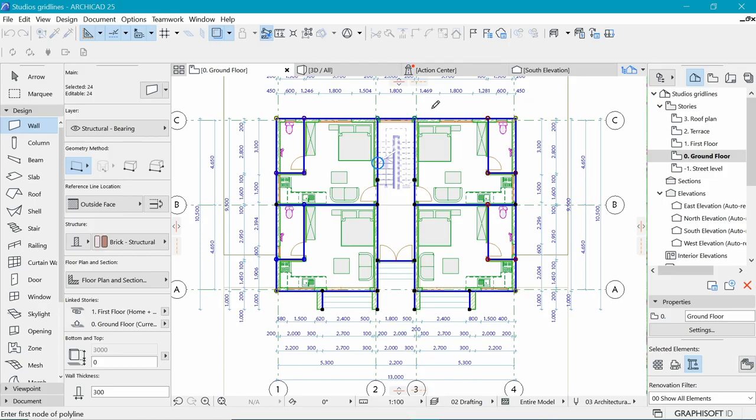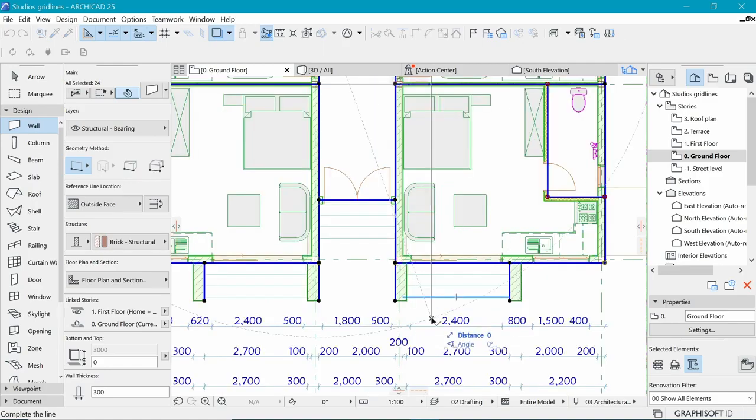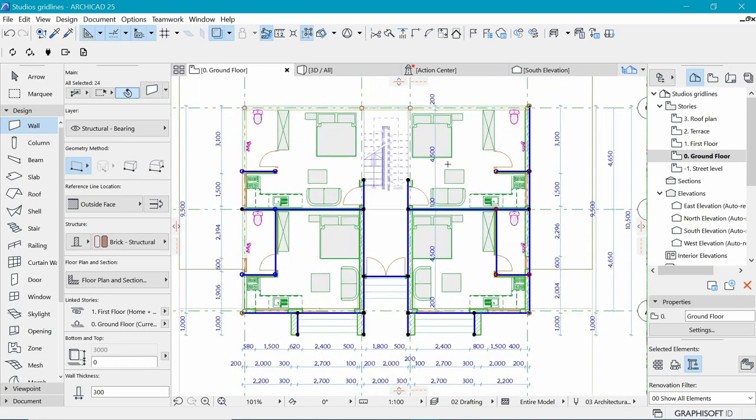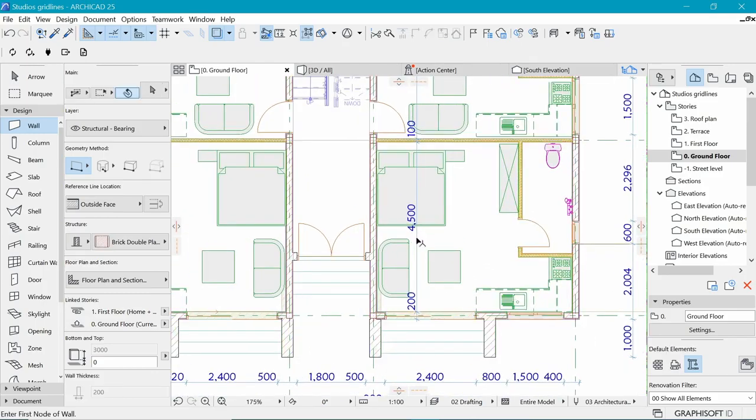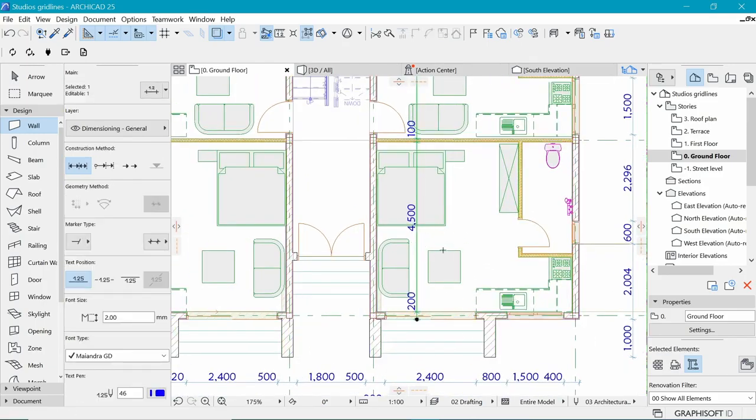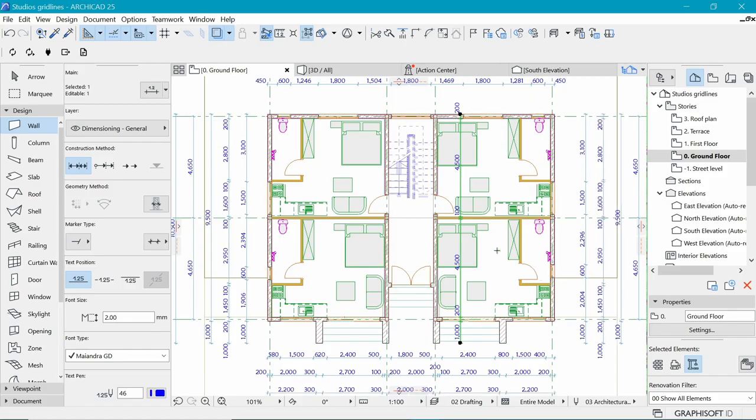across here. Okay, you draw a line, let's draw this line. I hold down Shift such that it's, you know, vertical. You can see this vertical line, and once I have done that, double click to finish, and then I place the dimension, and you can see we have ourselves that 200, 4.5, 100, 4.5, 200, and then we can complete this dimension by selecting it and holding down Control to add a node like this to specify that dimension, right?